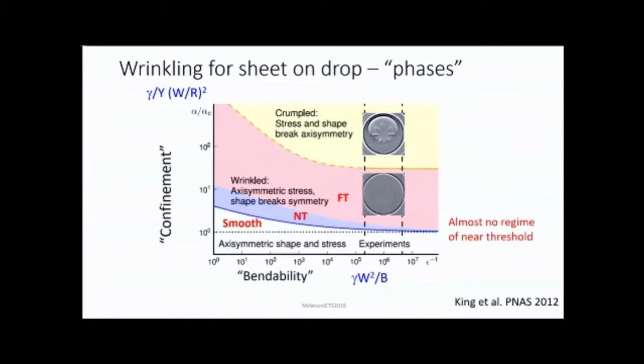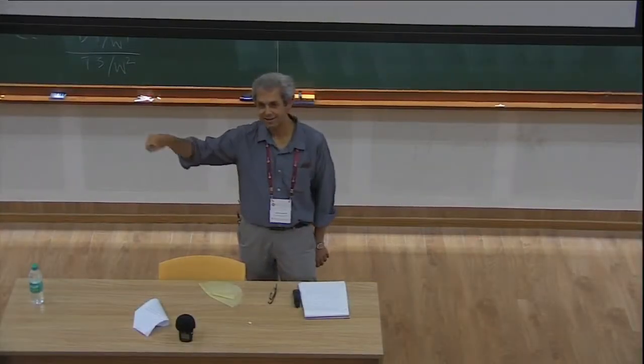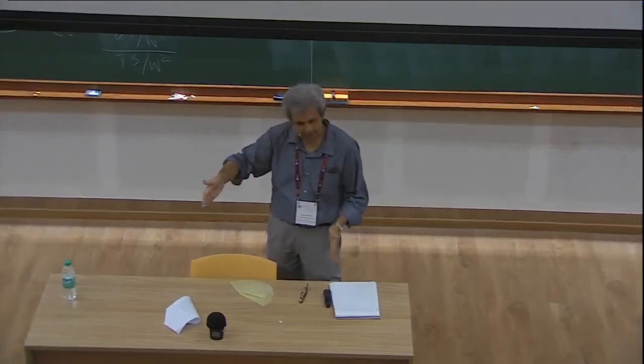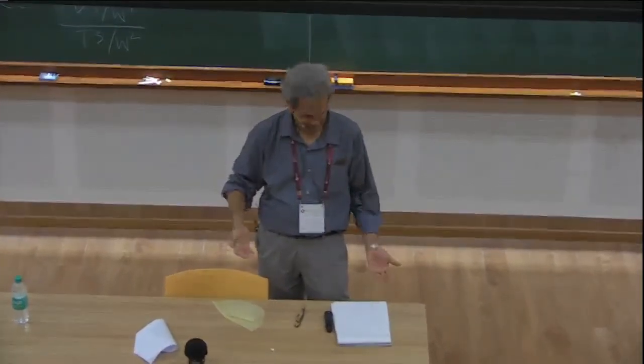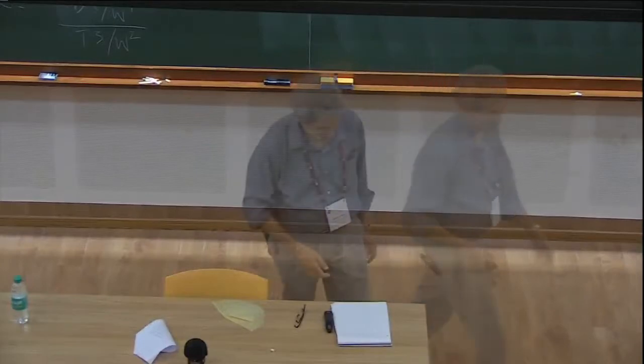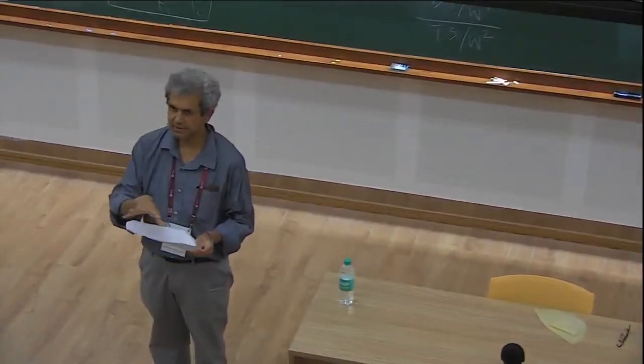So we talked about 1D wrinkling. Then we talked about how a delocalized solution in 1D becomes a localized solution in 1D, right? We talked about folds. I'd like to now begin doing the same thing for 2 dimensions. We talked about how a general state of stress in 2 dimensions can make wrinkle patterns in 2D.